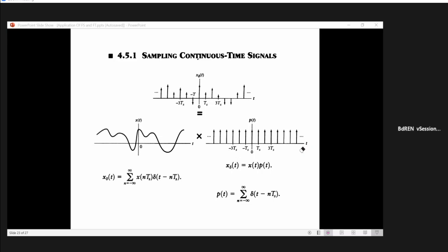Because your signal will be going there serially, isn't it? So when a sample is entering further processing, for example quantization or coding, it will take time, okay? Within that time, your signal amplitude may be thought of as constant, or we call it flat top type sampling. As a result, you have to hold it. Otherwise, if your signal disappears, then processing will not be possible, isn't it? So that holding is needed.